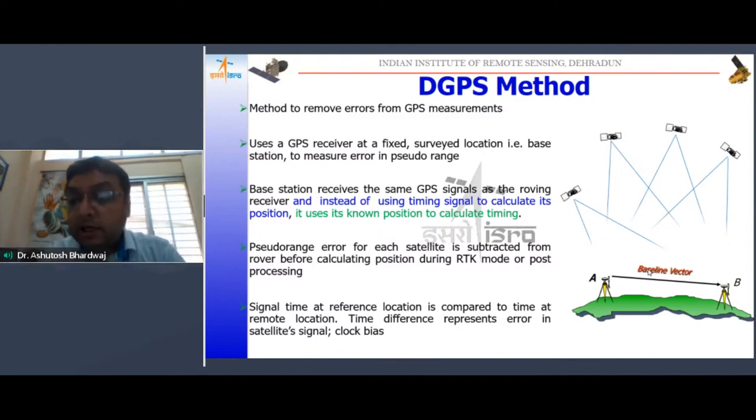If the quality of the signal is very good, it is between 1 and 3, in the table which I have shown you earlier, and DOP is utilizable by anybody. Expertise is not needed because it is displayed on the GPS receiver. Anybody from any field can understand that, and it is a unitless number also.